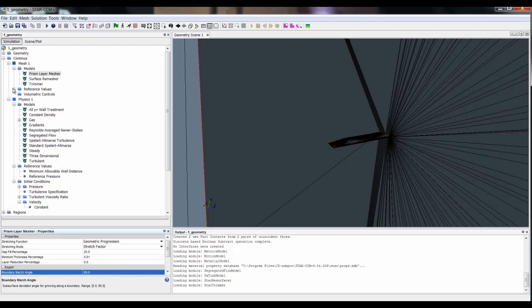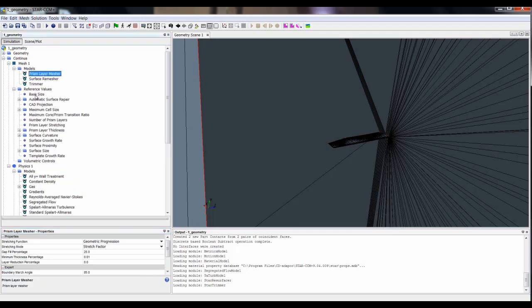After this, I can go to the next node down, which is reference values, and here I can specify my global mesh sizing. The upcoming mesh sizing and refinements I apply are specific to this wing under the given flow conditions. They are relatively coarse since this is being run on a laptop. Note that mesh sizing and refinements will change according to the application being simulated, the flow regime, computational resources available, and the level of fidelity needed.